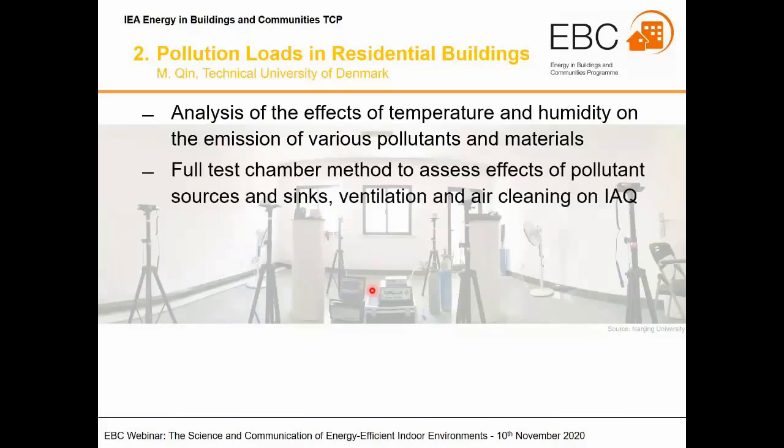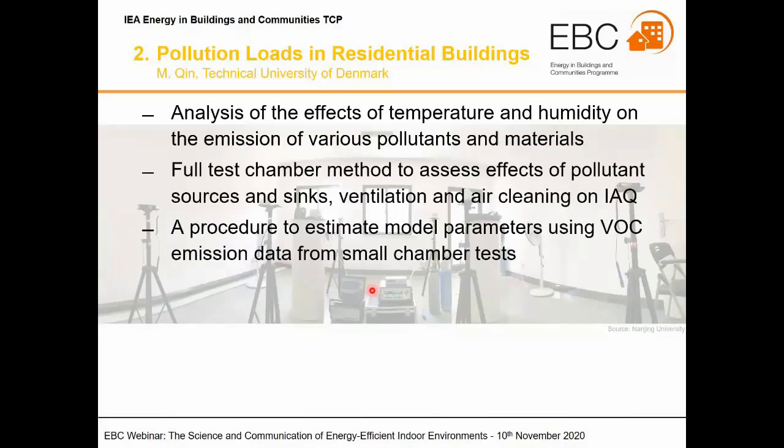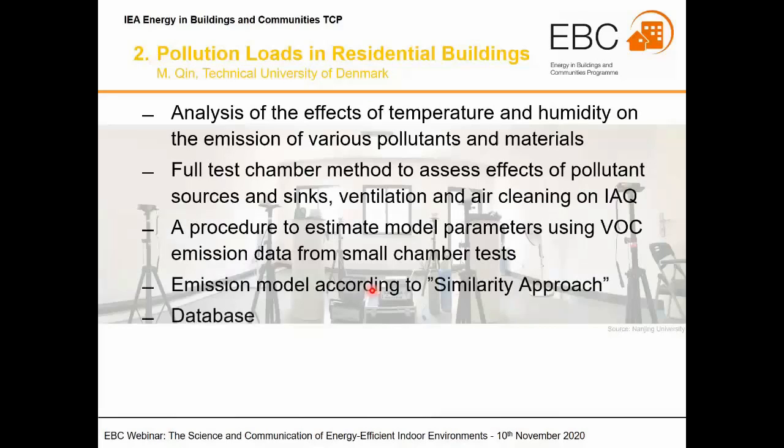So we had both some full-scale test chambers, like also you see in the background here, a room, but also laboratory test chambers were used to study emissions and sinks from building materials. We had also some small-scale chambers where we could study more the actual performances of individual materials. And then we tried to model that also to understand that, and we adopted a similarity approach I will present on my next slide, similar to how we are used to model other mass transports for materials also. And this was collected, some of the new information we got in a database.